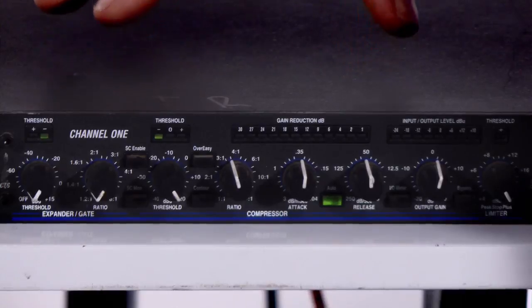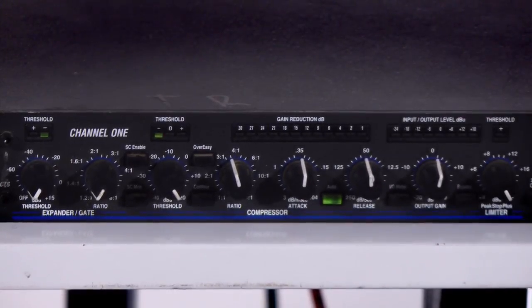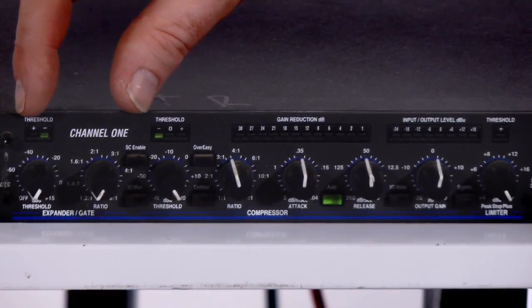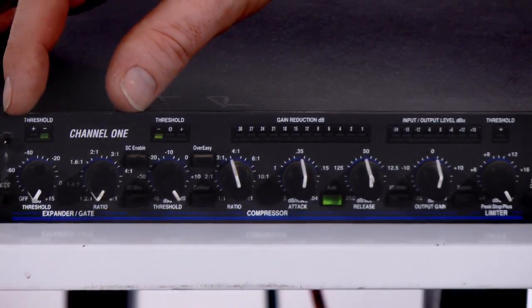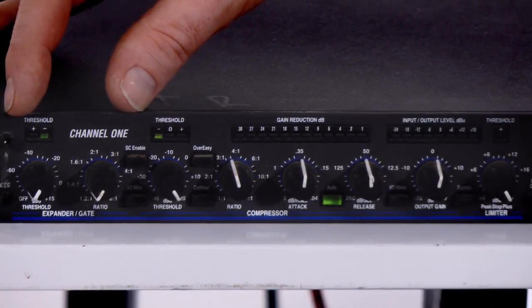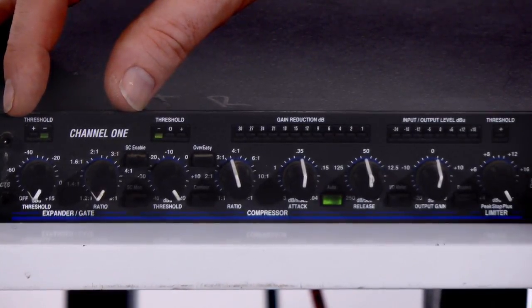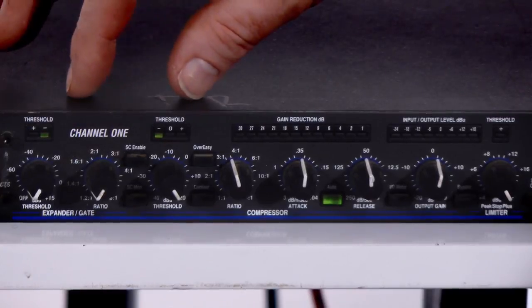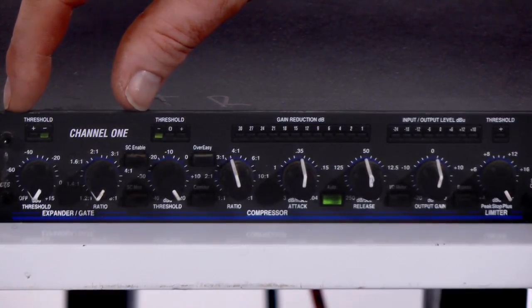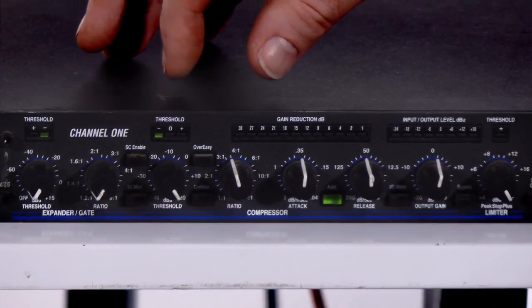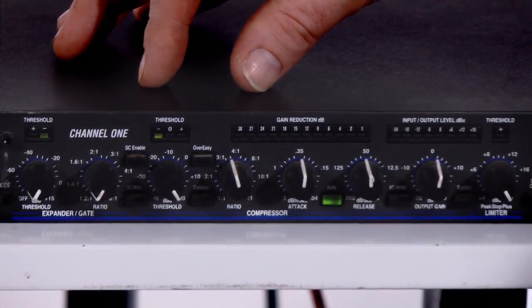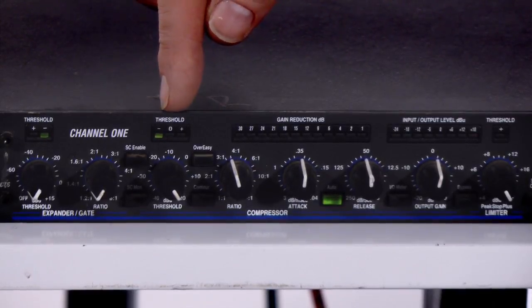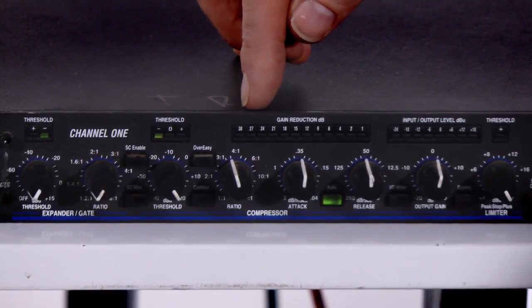This is the compressor channel that we've got inserted into by now our familiar microphone. Let's have a look together at the controls that we've got. Well, on a DBX compressor of this type, the first part of this is a gate. And we're not using the gate at all. In this example, we're just using the compressor function. So if you look closely at this knob, when it's turned anti-clockwise, the gate functionality is turned off. So we can immediately forget the first 2 knobs. The second 2 controls are the 2 important ones that I told you about. The first one here is the threshold knob, and the second one is the ratio knob.